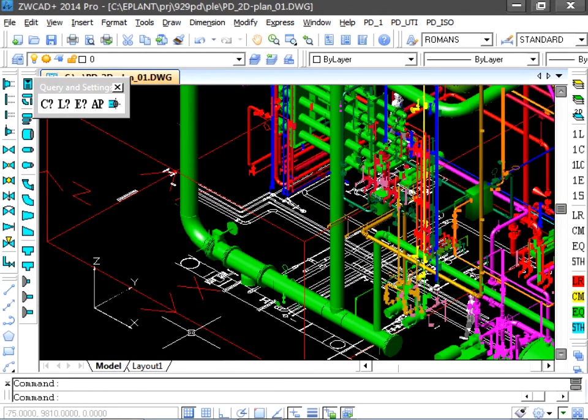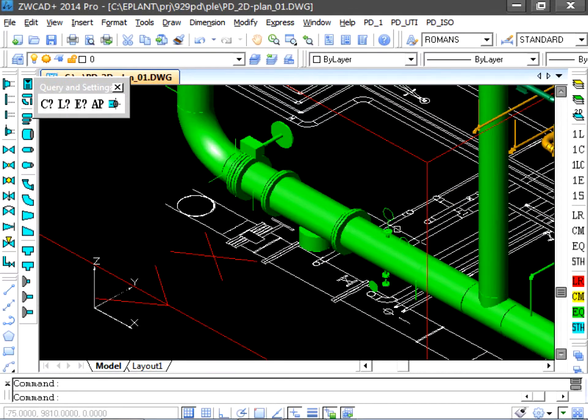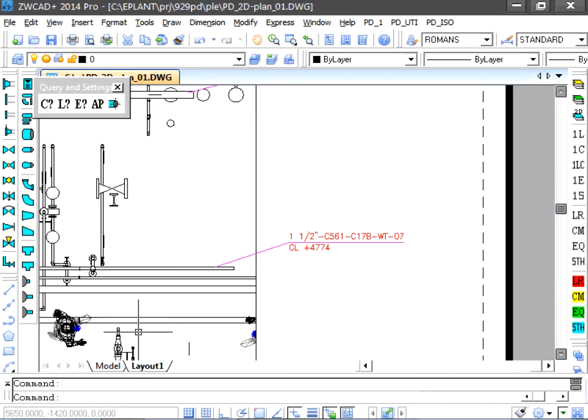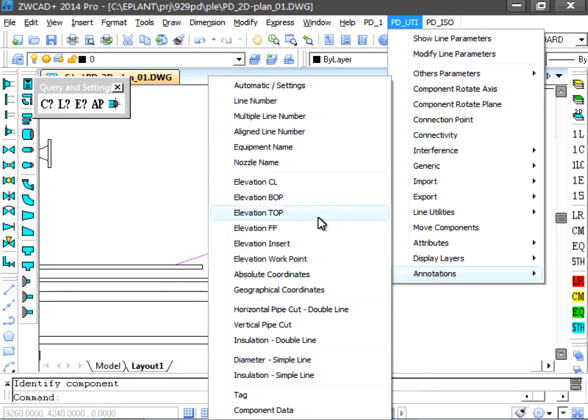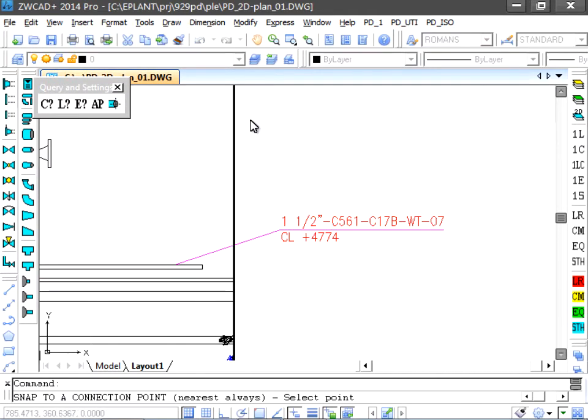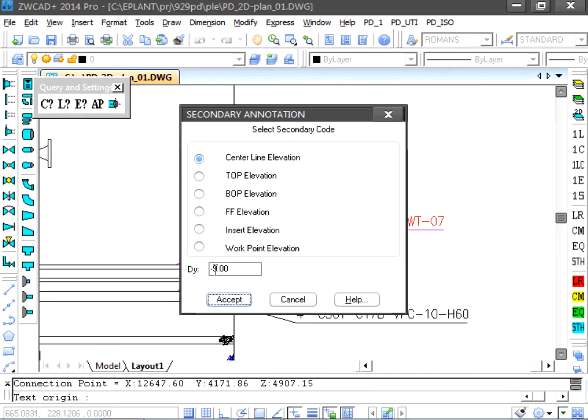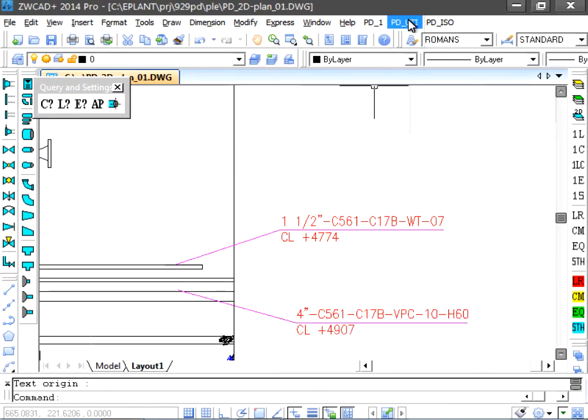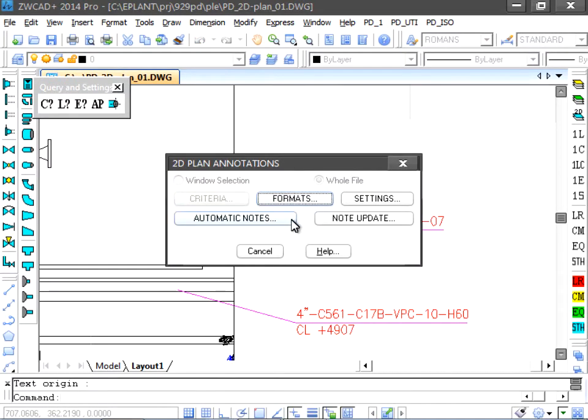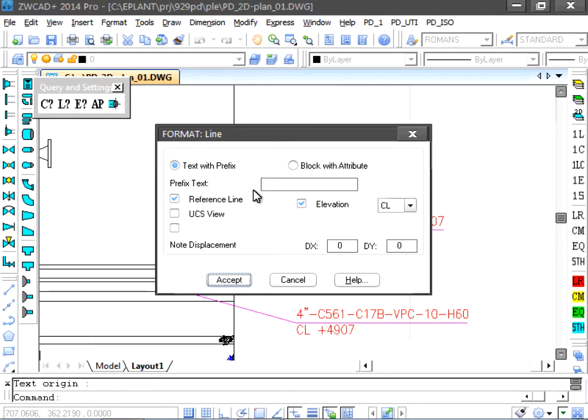The projected elements retain the 3D model data and can be dimensioned and annotated in Paperspace. Other options are available, such as to automatically place nodes, to update nodes if the 3D model changes, and node format settings.